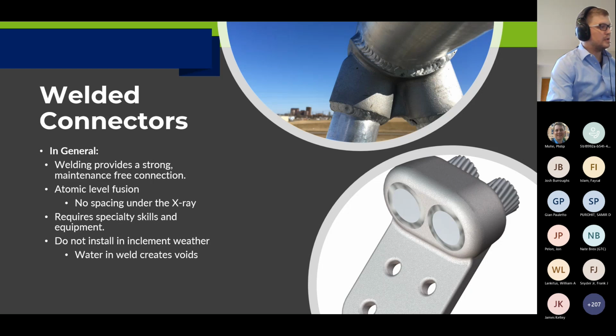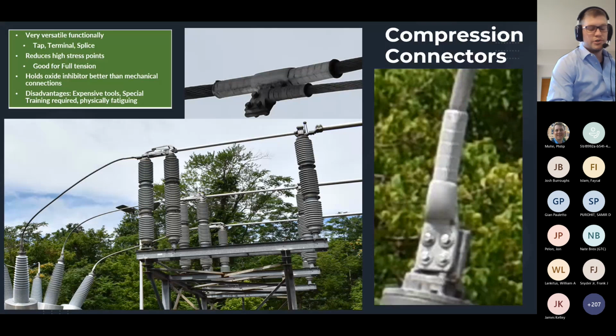But moving forward into another style, which is compression connectors. Compression connectors and swage connectors are pretty similar. I'll describe the differences, but both of them are very versatile. You can use them, in this picture, as a terminal connector where you're tapping off of the switch pad or onto the circuit breaker for a four-hole pad, or in this picture at the top here is an example. It's actually sideways. It's really coming from an overhead line coming down, and we did a compression T connector.